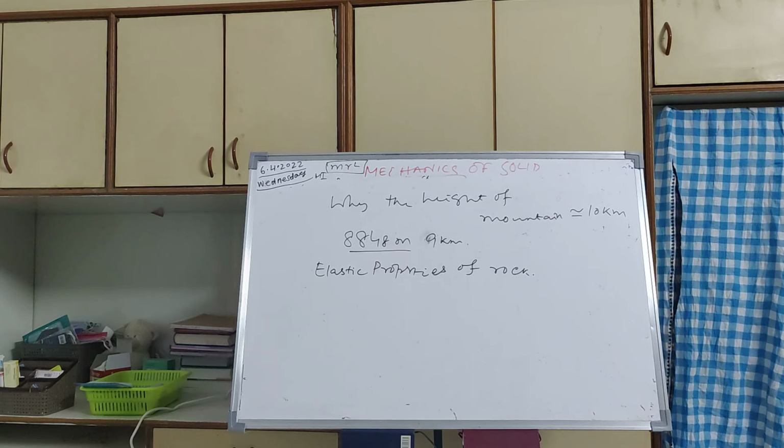Due to gravity, the material at the bottom experiences this force in the vertical direction, and the sides of the mountain are free. Therefore this is not a case of pressure or bulk compression. There is a shear component of approximately h rho g itself. Now, the elastic limit of the rock.